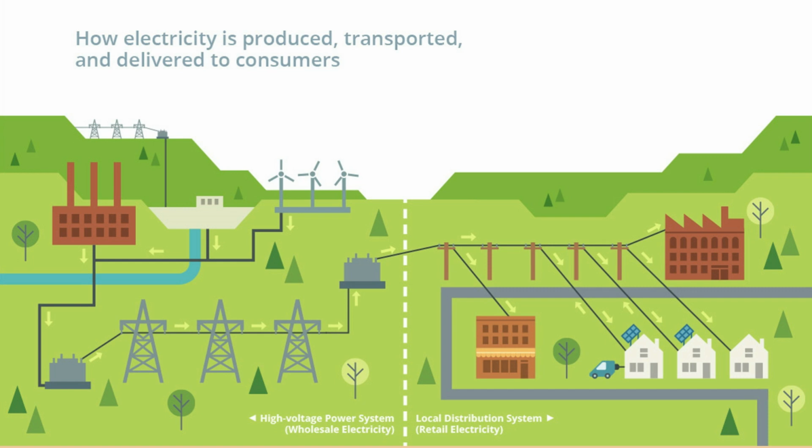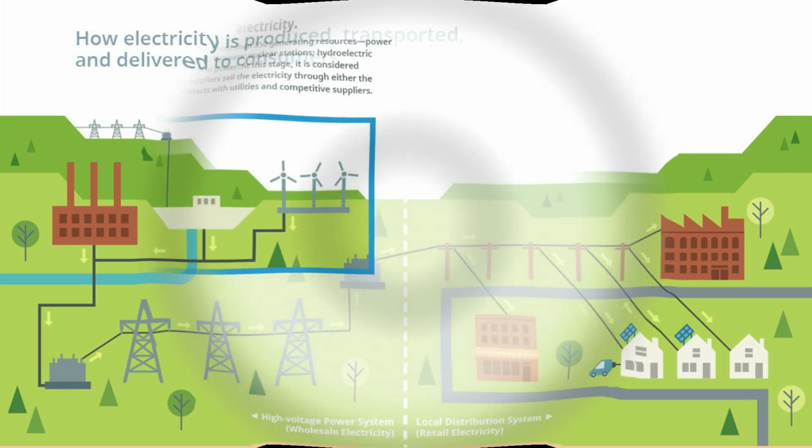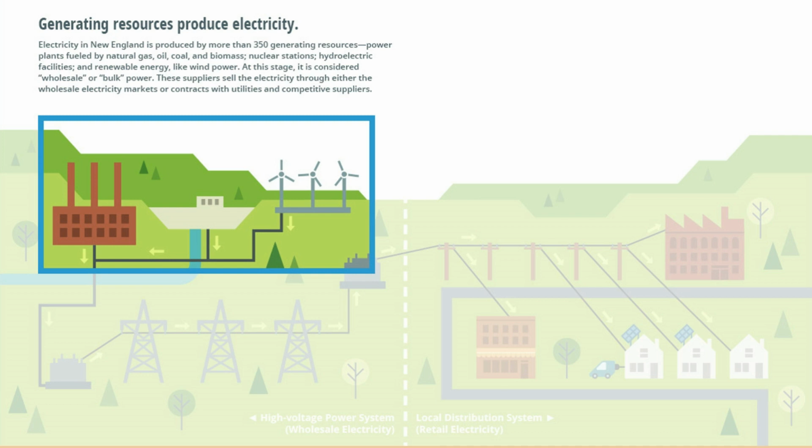What time is it in grid time? The grid time is often used as the basis for the time display on electrical appliances. In Europe, the grid time is based on the standard grid frequency of 50 Hz. A second corresponds to exactly 50 oscillations of the alternating current. Deviations in the grid time are caused by frequency fluctuations. If the frequency is less than 50 Hz, the 50 oscillations require a bit more time. At more than 50 Hz, they happen faster. The grid seconds therefore last a shorter or longer period, depending on the frequency.